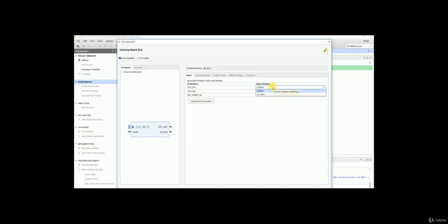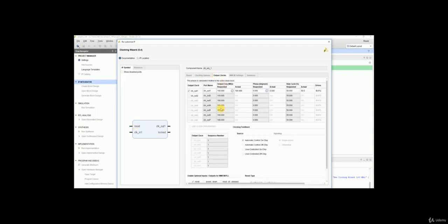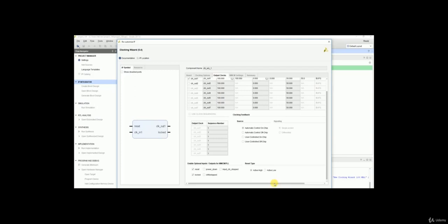Now Vivado is a hardware dependent software. As soon as you add a certain board, certain parameters are set by default. For example, you'll notice that for clk_in1, we have an option to directly select a sys clock. So it automatically identifies the clocking related pin, and the other thing that we always need to do is to take the reset to be active low. Okay, so this is the second mandatory step that you will always be performing.